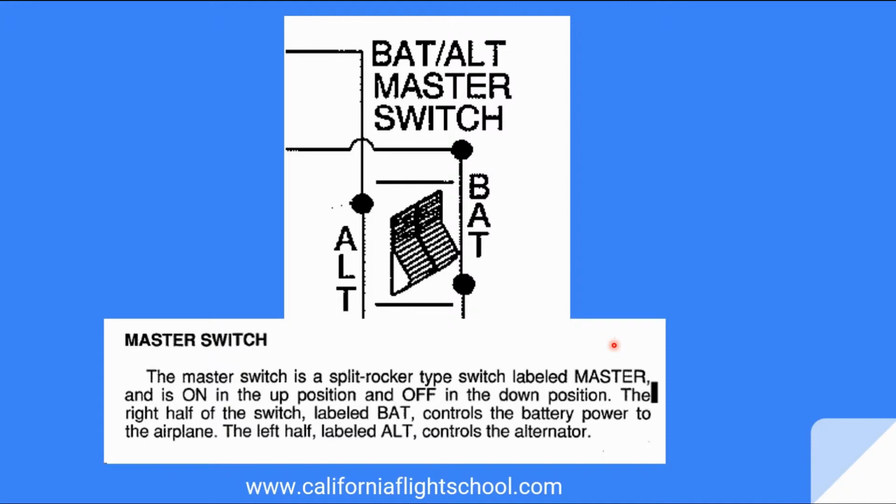And when you switch on the aircraft battery master switch during your pre-flight, the engine's not running, if you turn on both the alternator and battery side, and then listen on the side of the cowling near the J-box, you could hear some humming. Once you switch the alternator side off, you won't hear that humming anymore.